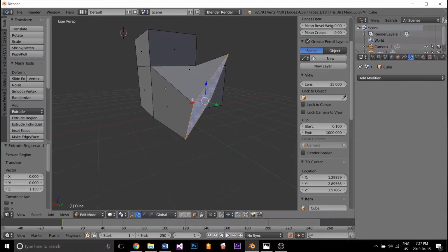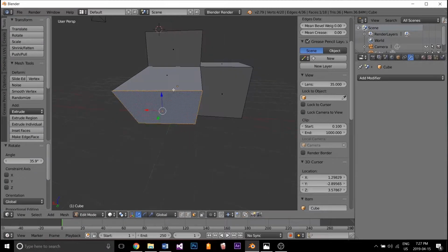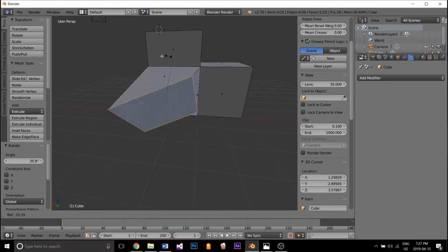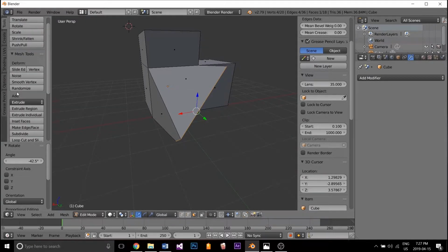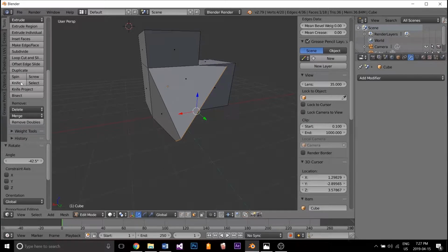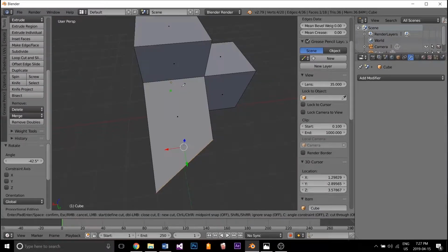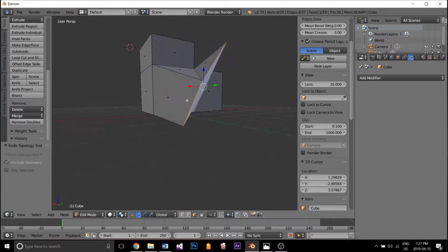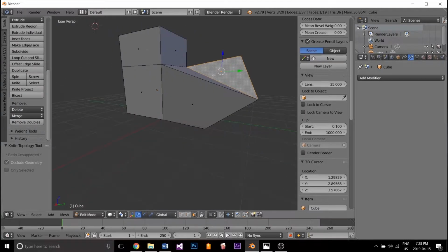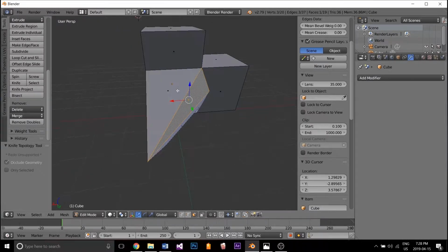To fix these, generally we can just rotate back the box and it'll fix the face. Another way to fix that is we can go into our toolbar over on the side in our tools, scroll all the way down, and hit knife. Using the knife tool, we go right into the corner, and this will auto snap to the vertice, and we can left click. Here we can draw a line to the other one, try and get right on the snap point, left click again, and then hit enter. This fixes that face that gets all weird after extruding and rotating on a weird axis.